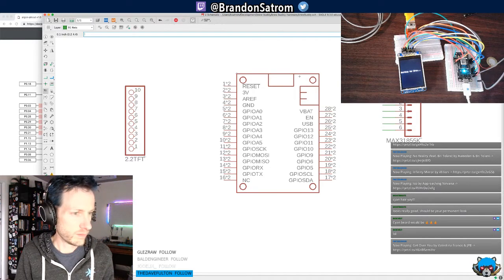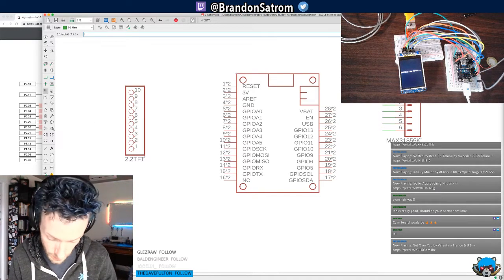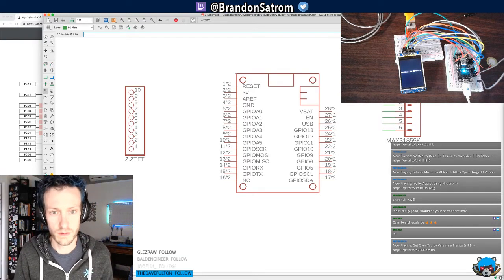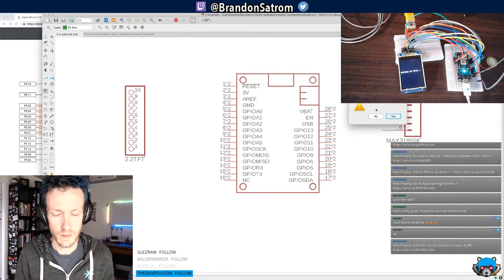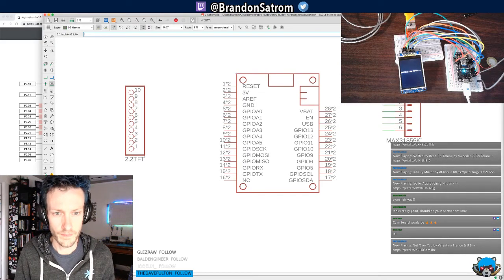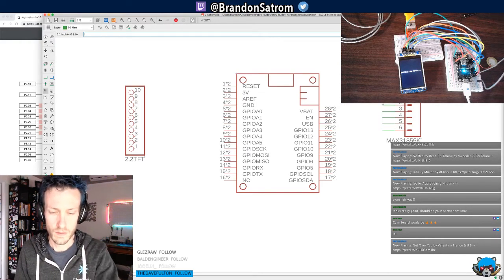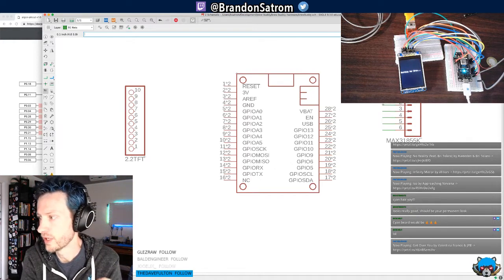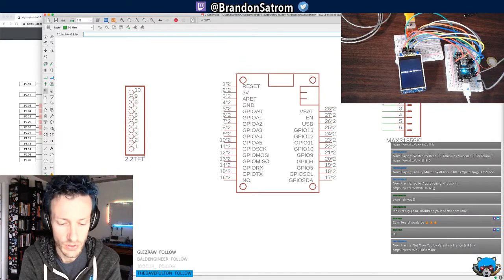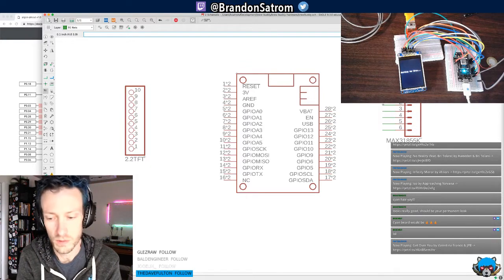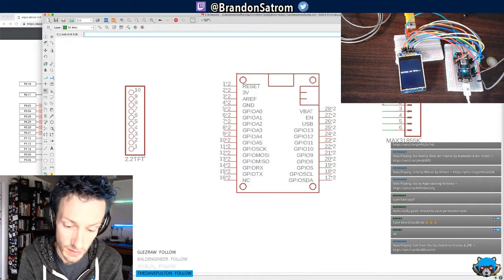So I'm gonna name this net ground. Yep. So what I'm doing here over the next couple of minutes is, instead of dragging wires like you saw here originally, I'm just going to use named nets to keep this a little bit cleaner. That was something that I didn't do a couple of years ago and since learned over the course of the last year or so. So we got ground, VCC, SEK,